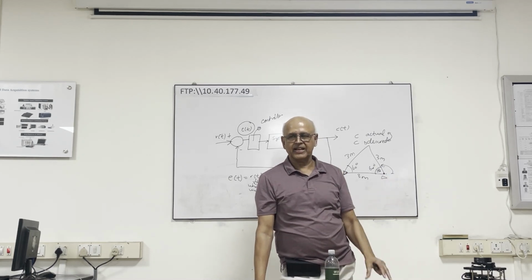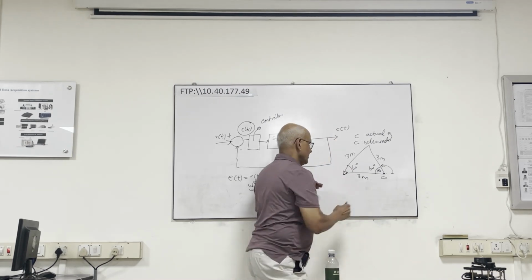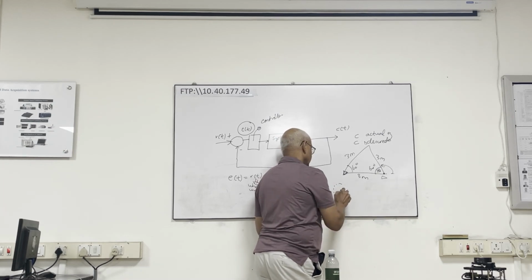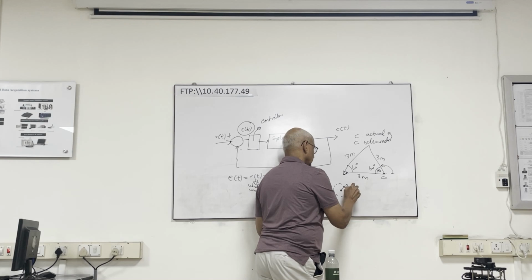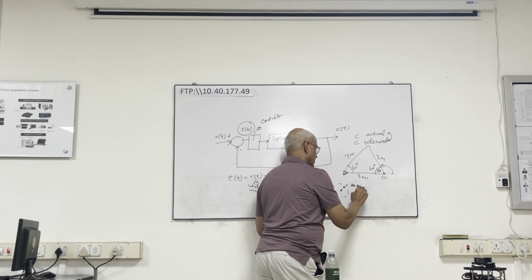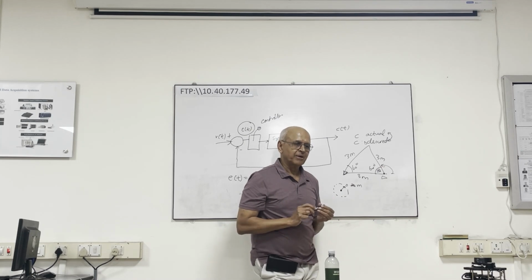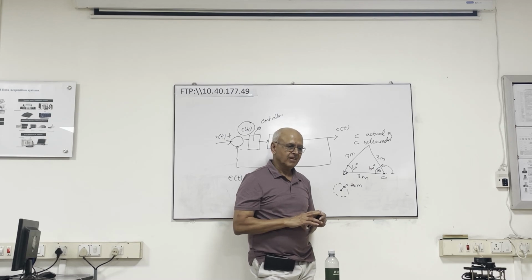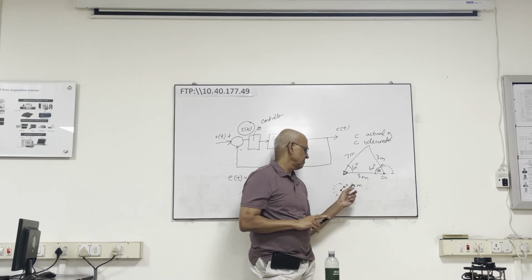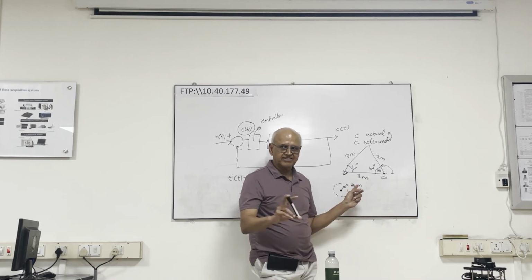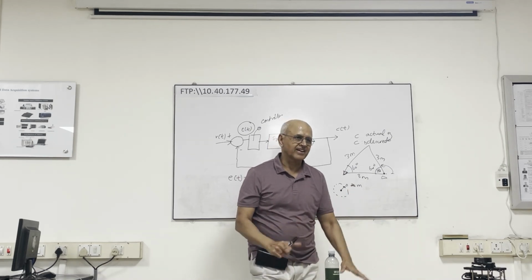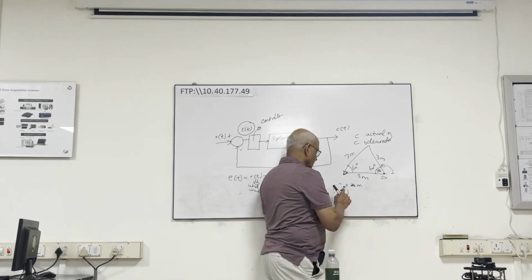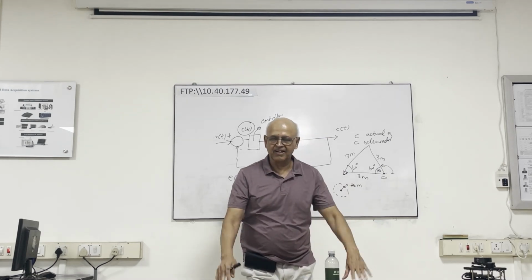So you have to monitor two things. You have to ask, okay, this node I'm producing here, right? You draw a circle around it. Maybe this is, sorry, not 0.02, that might be too tough, 0.2 meters. I'm saying if I'm within 0.2 meters, I have reached that node, right? So if I make it 0.1, it's tougher. I can't make it 0, right? You know that already. Nothing in the world is perfect. So 0 means that you're going to have a hard time reaching that point. So that means if it crosses anywhere inside the circle, you're saying, okay, I've got there.